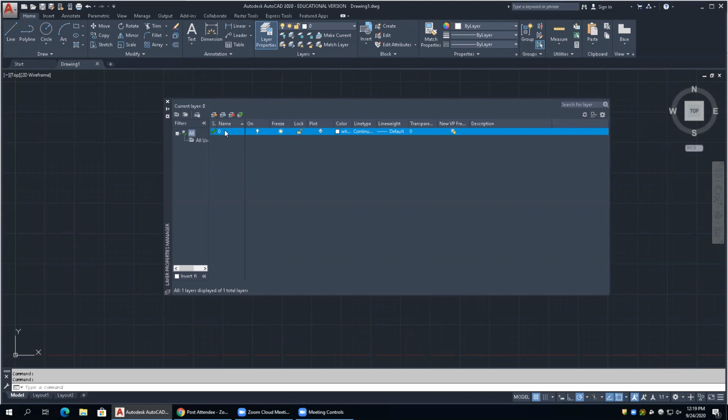Any other layer that you create can have any name you want associated with it. But AutoCAD will just call it layer 1, layer 2, layer 3, layer 4 as you create them generically, and then you can go back and rename them. So I suggest when you get your layers, you name your layers coincident with something that's going to be on that layer. For instance, waterline. So if I name my layer waterline, then I know what's on that layer should be water lines or building or tree. You get the idea?